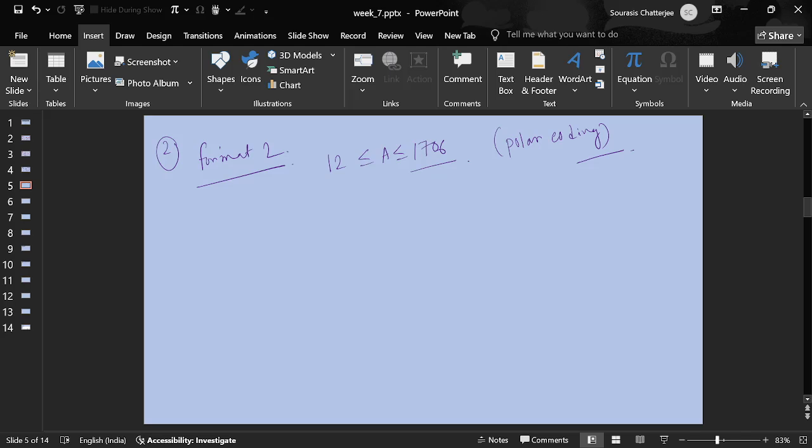Yes, because you have to send the subband CQI, or subband CSI, for every subband. If you have 15, 16 subbands, each subband has 16 PRBs. You have to send at least 16 into 4 kind of things. Correct. In every subband you have to send some absolute inputs. Correct. Exactly. So in this context, if we think from this perspective, in downlink control,